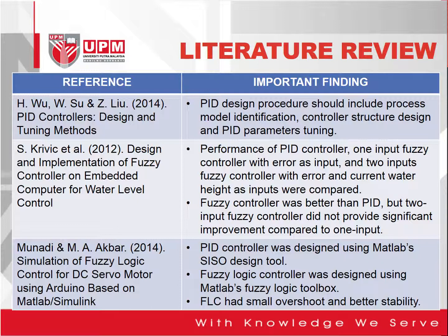And then in 2014, Munadi and Akbar, in their paper Simulation of Fuzzy Logic Control for DC Servo Motor using Arduino based on MATLAB Simulink, designed their PID controller using MATLAB's Single Input Single Output design tool, and the Fuzzy Logic controller using MATLAB's Fuzzy Logic toolbox. They found out that Fuzzy Logic control had smaller overshoot and better stability.